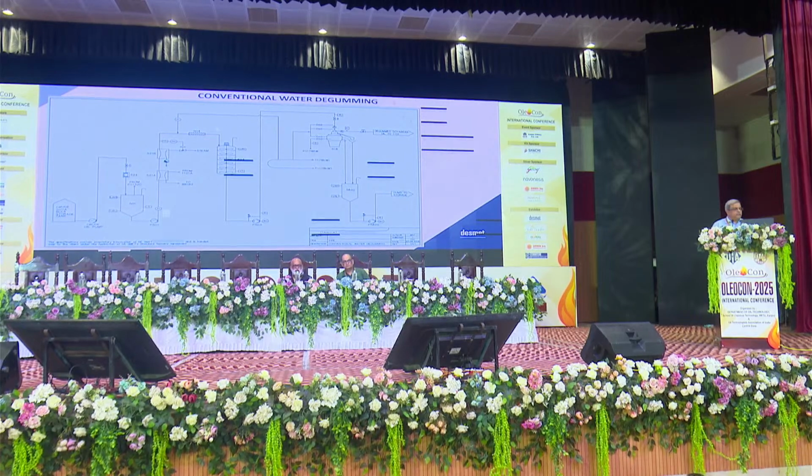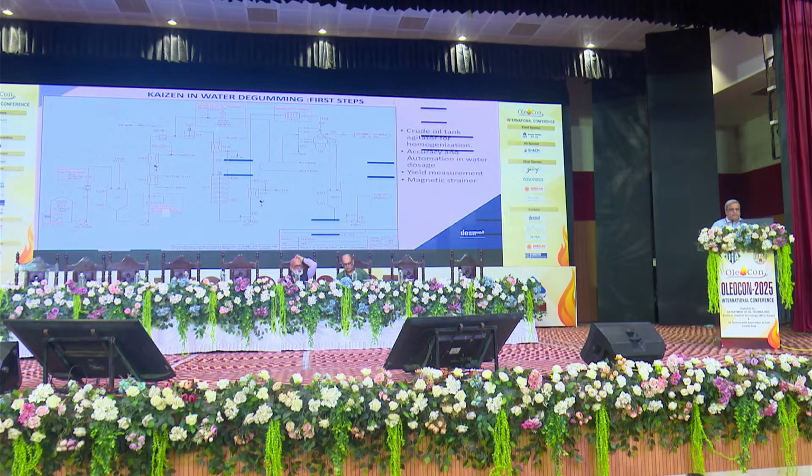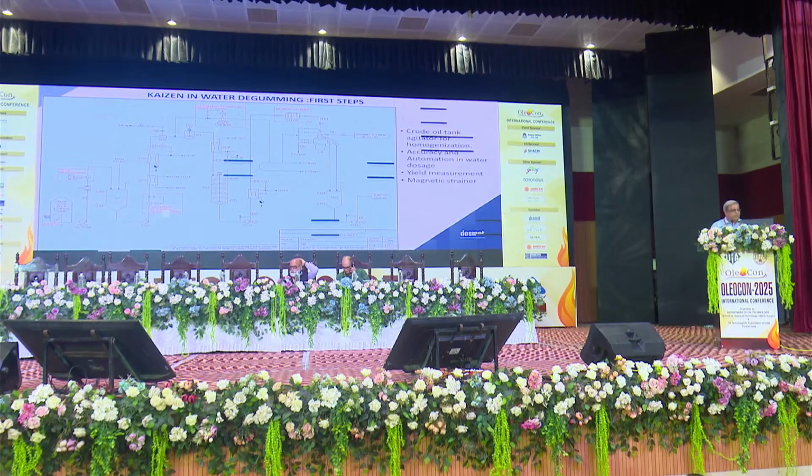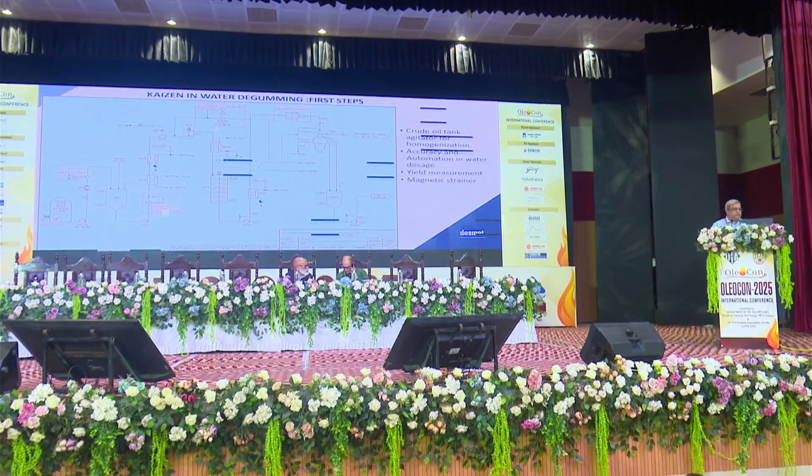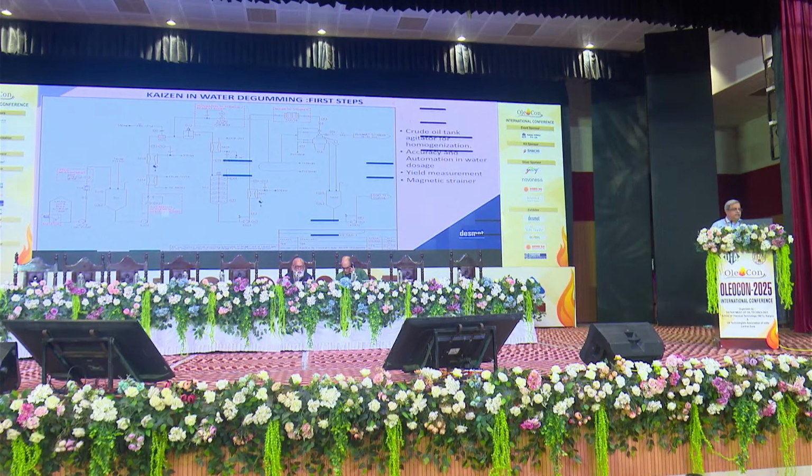Starting from the bulk tank, day tank, the heat exchangers to heat the oil, water mixing, hydration, separation of the gums. These conventional plants can be upgraded by adding a mass flow meter in the inlet to improve the yield measurement, adding the side entry agitators in the bulk tank, which is very important to have a homogeneous oil coming to the plant. So a side entry agitator can greatly help.